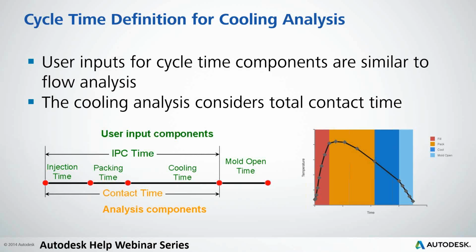The first three steps are what we call the contact time, and this is what we are simulating in Moldflow. We are not simulating the mold open time. We only add it as a boundary condition, a parameter, for how long it is, or we could let Moldflow simulate how long the time needs to be based on some settings for these three steps.